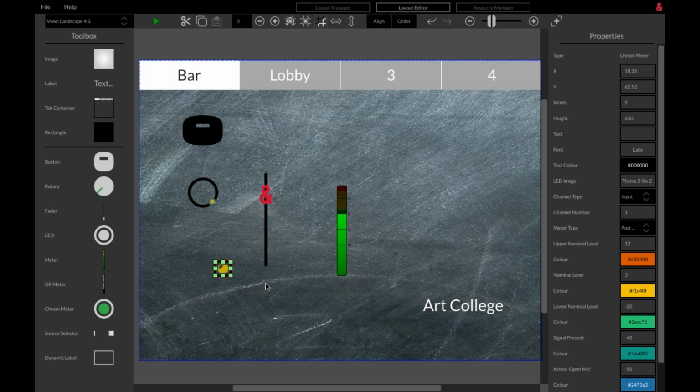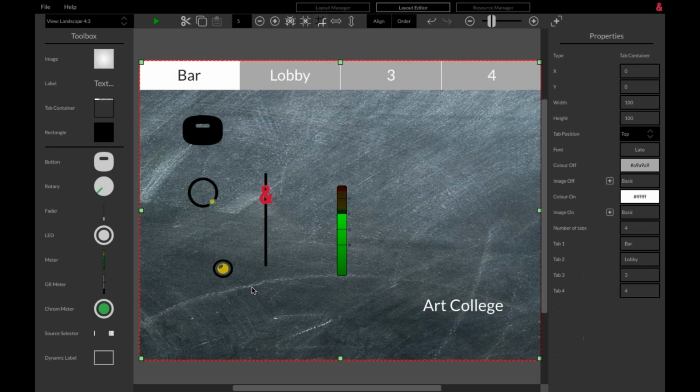But also in this case, because it's a chromatic channel meter, you can set the thresholds and the colors for your signal metering. So a chromatic channel meter was a way in the SQ design process where we could pack a lot of metering information into a single point source LED with variable brightness and color. And we thought that this would be very useful in custom control as well. So you can pack a lot of metering information of many channels into the smallest possible space.